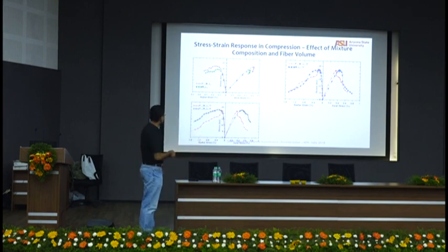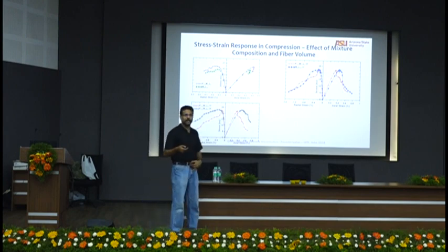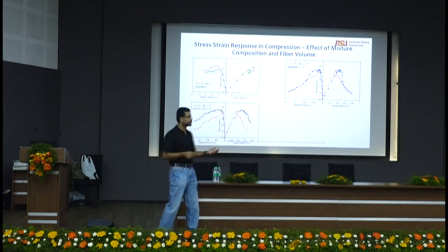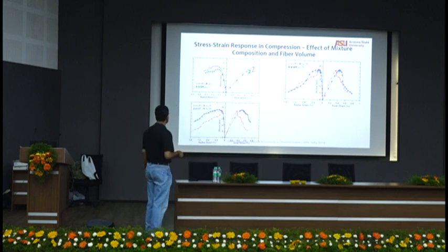So you can see here, even if you want to use the maximum usable compressive strain, you still are okay, right? For design. But because of the very high strength, you would not want to get to 0.3. You would want to stop at a much lower strain. You probably would want 0.25 or so, and that's fairly good.